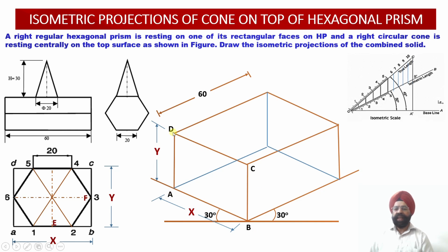Now once we have drawn the front face, we have labeled this as A, B, C and D, and now let us first of all work out the points corresponding to the rear face. They happen to correspond to A over here. We have A1 at the back. Corresponding to B in the front face, we have B1 at the back. Similarly, you have C1 corresponding to C and D1 corresponding to D. So all the points of the rear face have been located and plotted. Similarly, all the points of the front face rectangle have also been plotted.